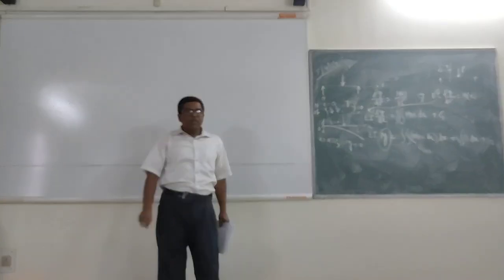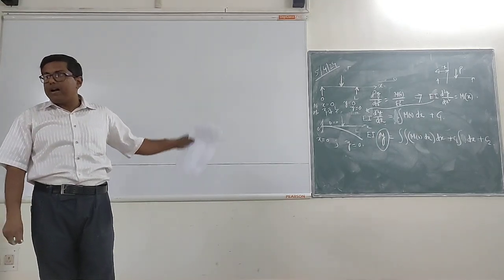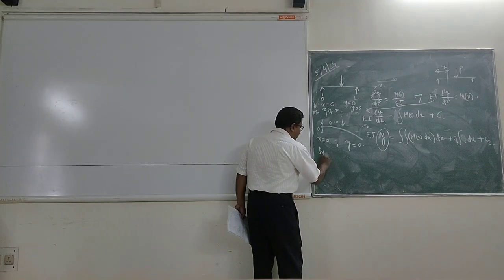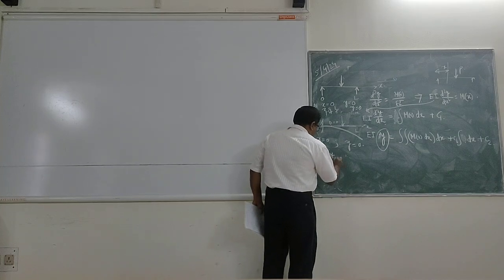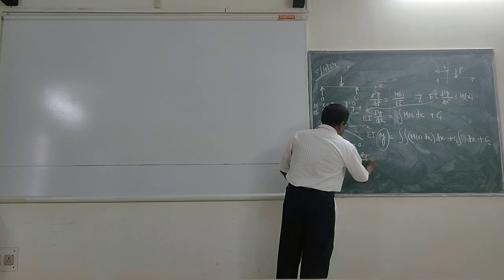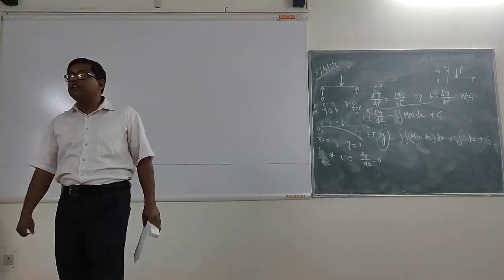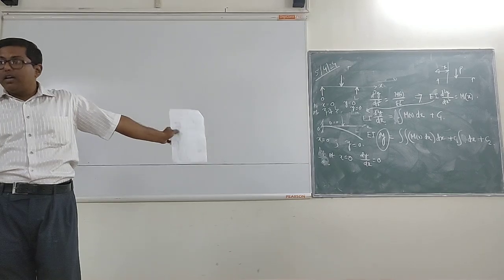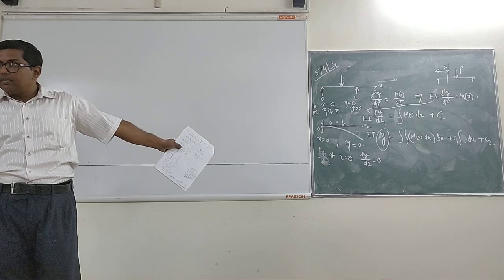What does it mean? The slope at the point where the fixed support is there, that is what? Slope at that point is nothing but dy by dx. So basically, again the boundary condition will be at x equal to 0, the dy by dx value should be equal to 0. Have you understood? So this is the boundary condition for cantilever. Any confusion on this? Have you understood the second boundary condition? What I have told, is it clear?